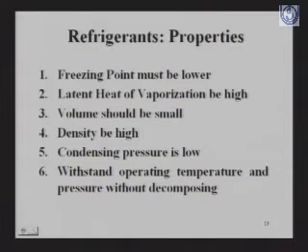What characteristics should the refrigerant have? The first thing is the freezing point must be lower. Then the latent heat of its vaporization should be high. Its density should be high, volume should be small, the condensing pressure is low, and it should be able to operate at temperature and pressure without decomposing. We call them the thermal properties of the refrigerant.